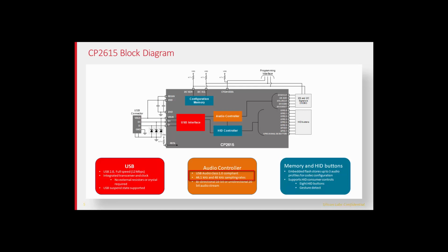The difference between USB audio class 1 and audio class 2 is mainly one of bandwidth. So if you really needed to have tons of audio channels with 24-bit plus playback, then the 2615 isn't for you. But if you look at the standard driver in Android, it's a 48 kilohertz sample rate, 16-bit driver. This is kind of a point where we've already reached a level of audio fidelity that works fine for most customers.